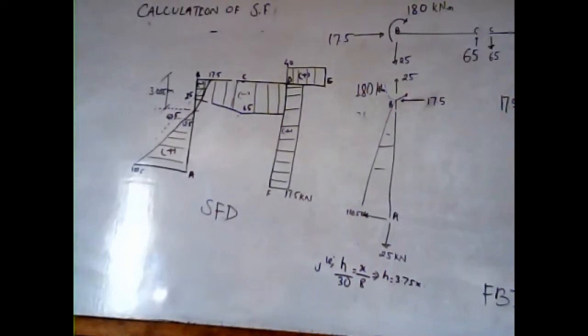In the section AB, we find out the orientation of the square parabolic curve. So at x equals 4 from A or B, at the midpoint, we have the ordinate of 12.5. We have just determined the ordinate 12.5, and if it would have been a straight line, the average ordinate of shear force would give us 42.5 kilonewton.